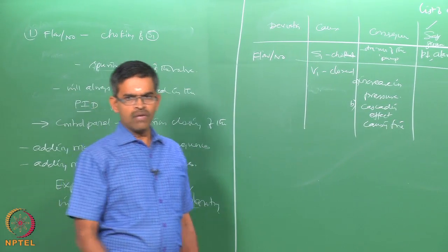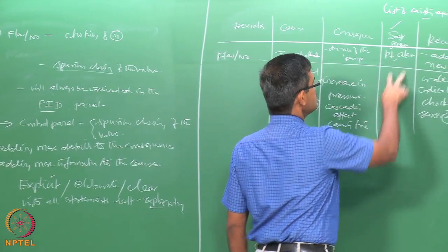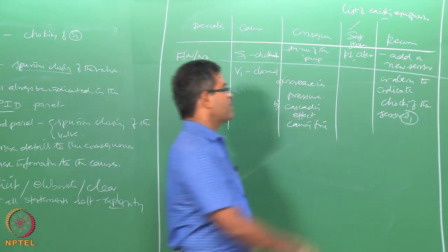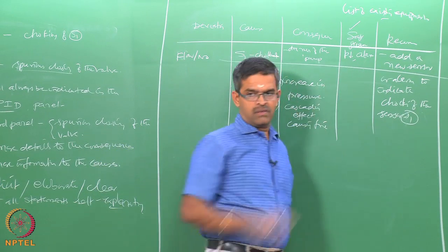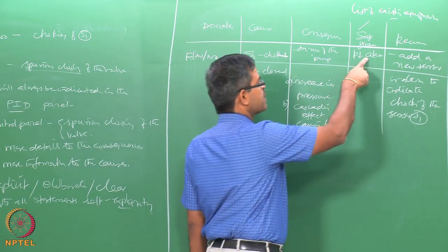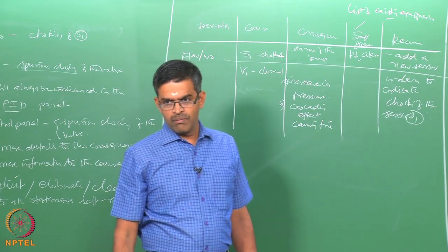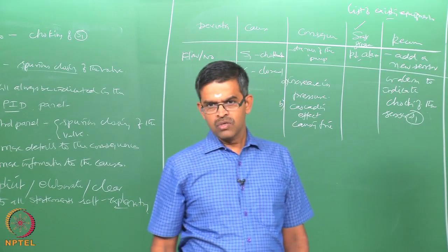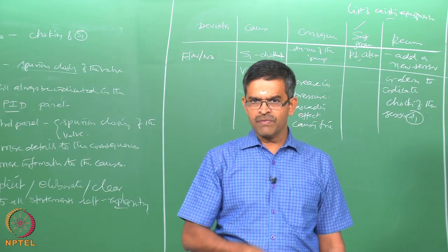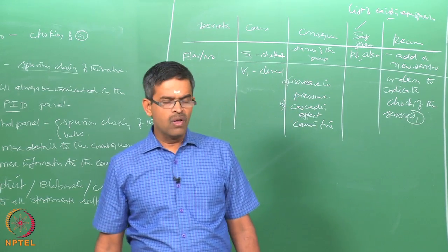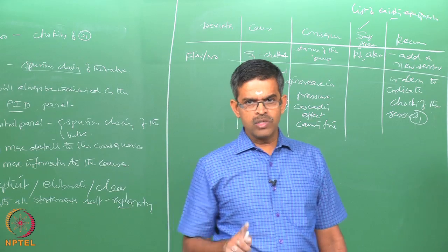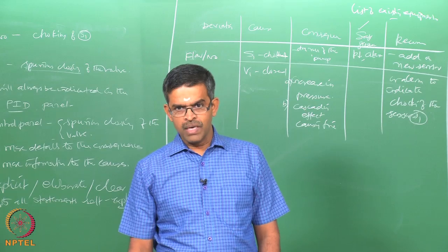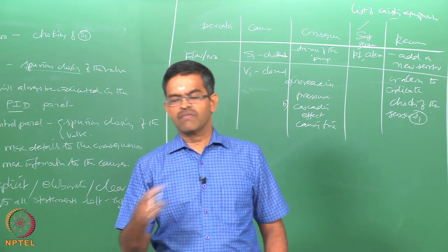So, therefore, it is always better to add on additional safeguards in the recommendation column in spite of presence of alarm system which is already existing in the given flow line, because with all these present in the flow line we are unable to maintain the flow, that is the deviation. So, we say flow no. So, it is always better to add additional safeguards in spite of the presence of alarm system in the control room. Therefore, while recording Hazop reports, friends, one should not take the credit of existing protective systems or instruments that are in place, but recommend additional alternate safeguards.